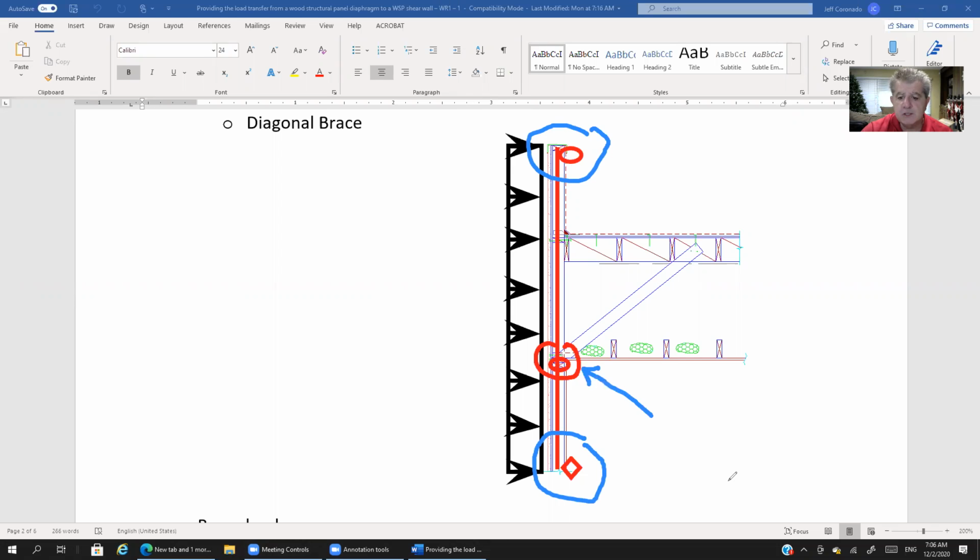We've got a hinge in the middle of our beam. Our beam is unstable. So the double top plate, in a way, introduces an instability for this beam. So what we need to do is add this brace in order to take the horizontal thrust.